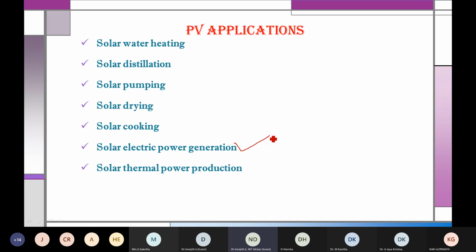Whereas when you go for refrigeration, now we have solar based air conditioners. There also we can think that the solar is used for generating electric power, and that is used for an air conditioner. That is not the case. The heat from the solar energy, that is from the sun, is utilized for boiling some ammonia or some refrigerant.